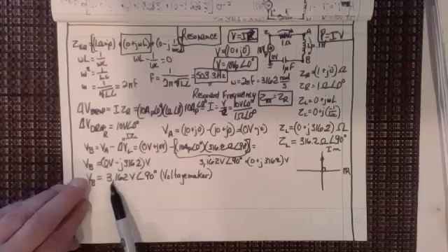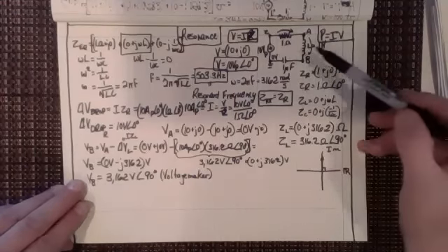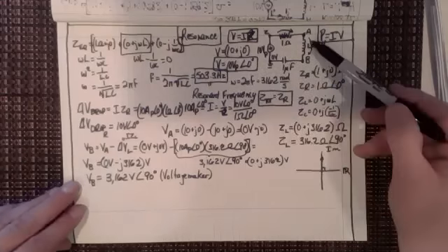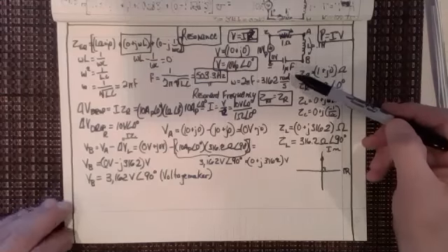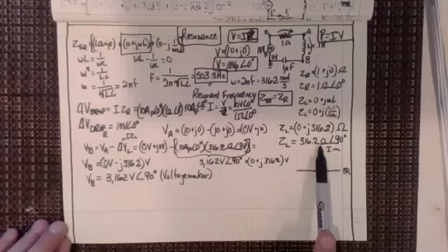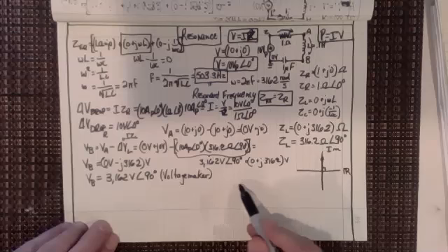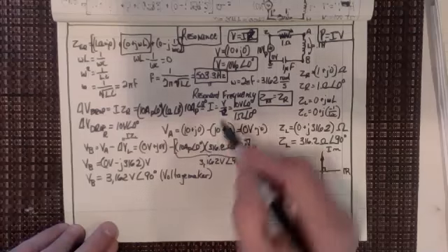But I could get this much higher, couldn't I, by just changing this to a 1 Henry thing, and then running it at a different frequency that would make the 1 Henry and the 1 microfarad better, because in the end, I'm always looking back to this. So you can see how you can change that and modify it. The truth is, there are no perfect inductors. You're always going to have resistance with any inductor because it's wound with regular magnetic winding wire. So that's going to be a problem, right? Okay. So I just wanted to point this out and show you what resonance is.